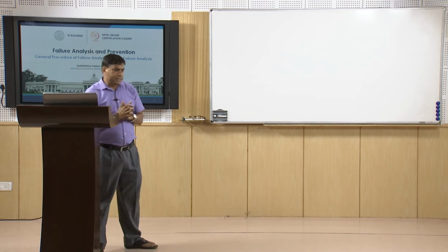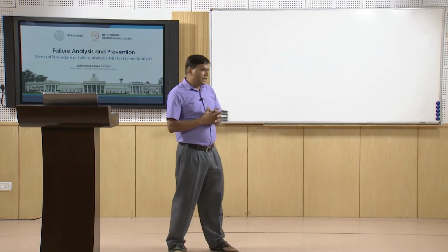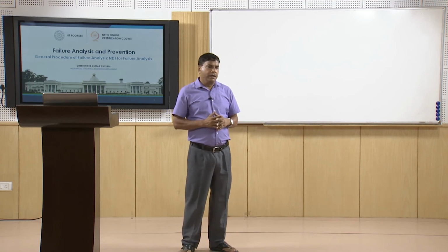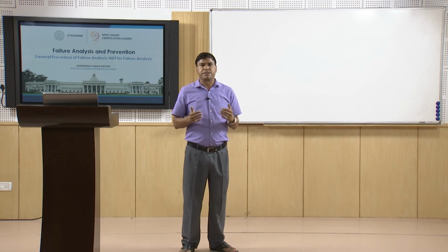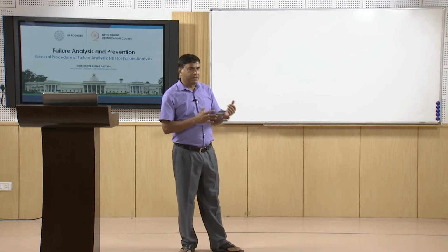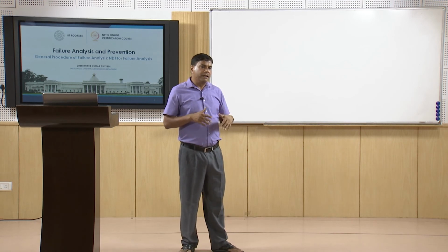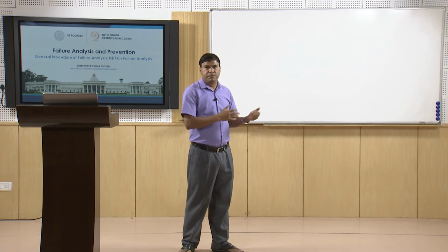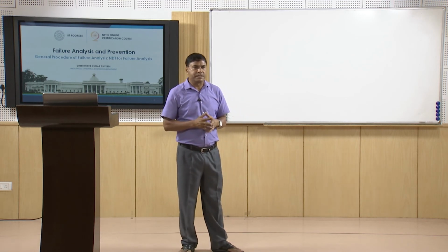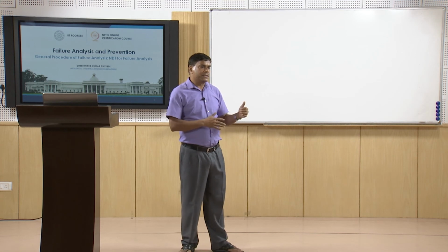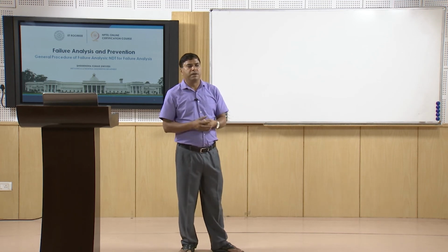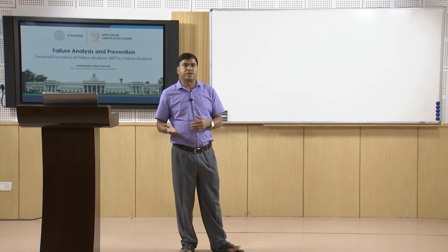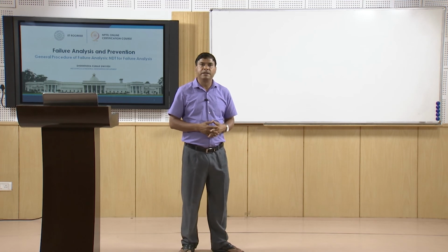In this presentation, I have talked about the need and importance of NDT in failure analysis. NDT helps to identify the presence of defects and discontinuities in the failed component, and efforts can then be made to relate these discontinuities with the possibility of failure through the fracture mechanics approach. Also, there is a stress analysis technique which helps to determine the load, stresses and strain experienced by the component during service.